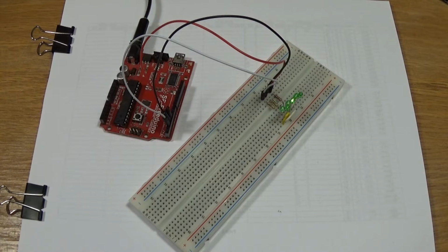All 3 timers can produce 2 separate PWM outputs, so you get a total of 6 different PWM outputs from the microcontroller. And in a later video I think I'll show you how to program the timers to give you the PWM. But for now, what I'll do is show you how to program the actual registers that control the timer, and I'll pick an arbitrary number of a 10 millisecond delay. An interrupt every 10 milliseconds, and then you can count the number of 10 millisecond interrupts to give you something longer. In this case 500 milliseconds, so you would count 50 of those interrupts and it will give you 500 milliseconds.